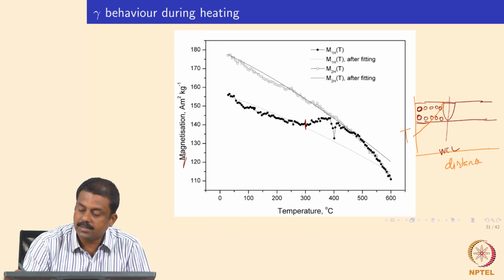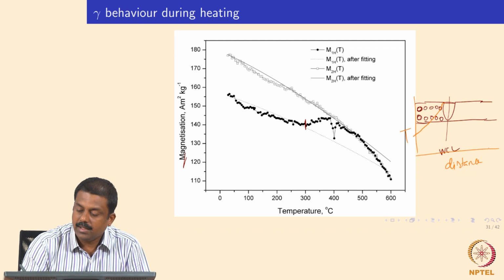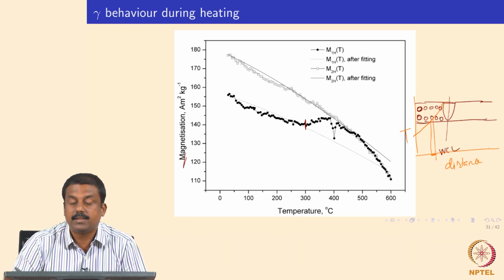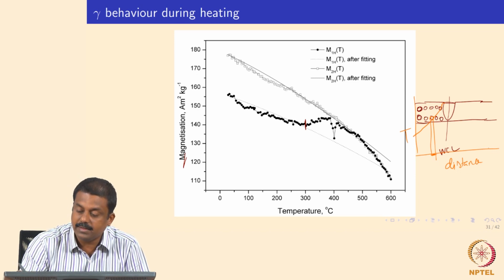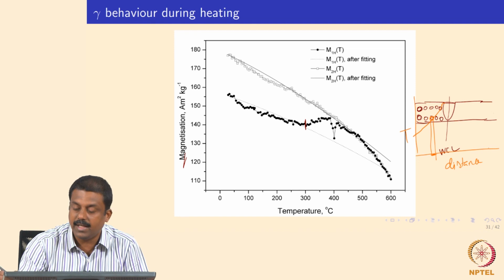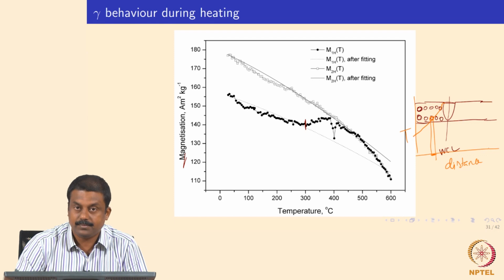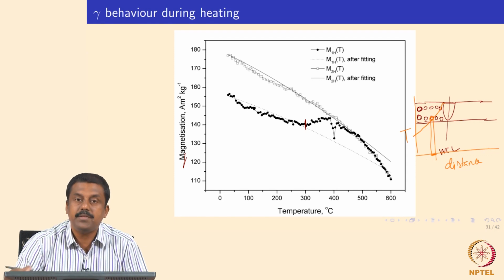If you look at this region, the temperature would vary by say 100 degrees or so. If the sheet thickness is say 3 millimeter, and you take a 1 mm diameter sample from the weld zone, along that 1 mm you may have a variation of 100 Kelvin. So, you are averaging the measurements over wide regions.